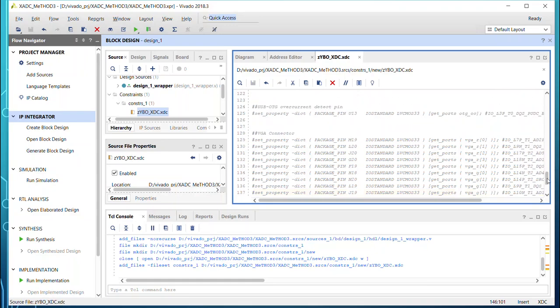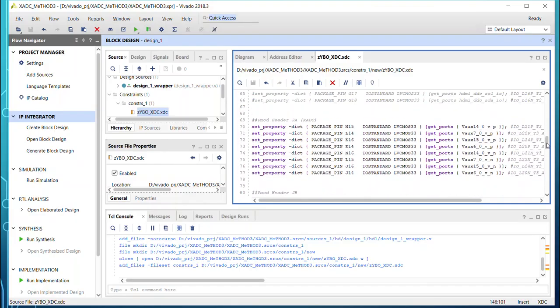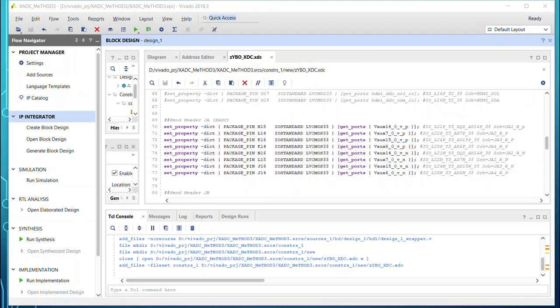If you go and find the part that is related to XADC, you could see all we have explained in this tutorial, for example, the different equivalent ports of the PL of this Zynq device on the Zybo board in 15 and also in 16, which was connected to VAUX14 P and N, all should be defined in this constraint file.